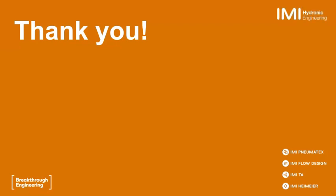All right, next we have: how does the use of variable flow pumping and the placement of the DP sensor controlling pump flow affect the valve selection or types of valves? That's a good question, because for sure we need to have a VFD to save energy in low load conditions, and we will have a delta P sensor installed somewhere to tell the pump when to slow down, right? For the balancing valves, it doesn't affect anything at all.